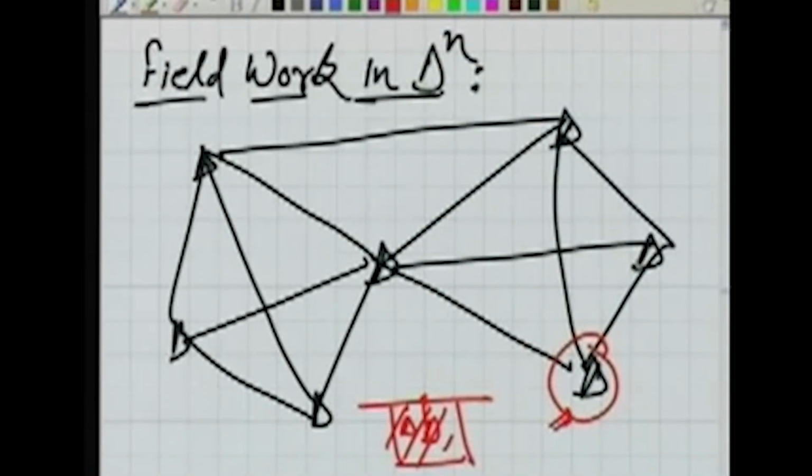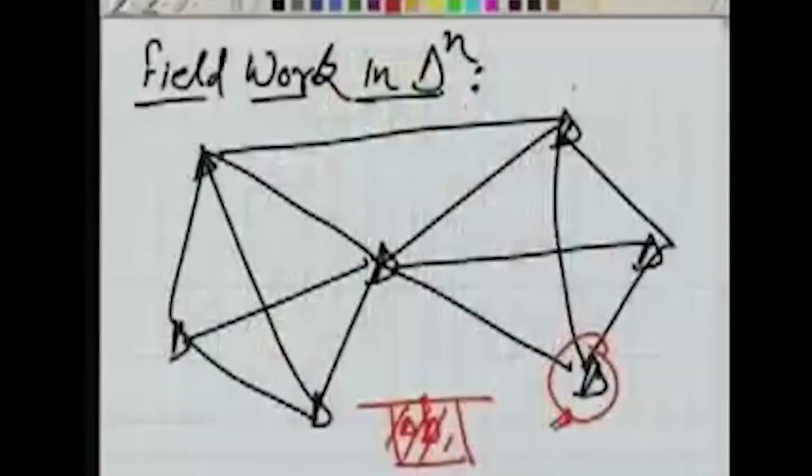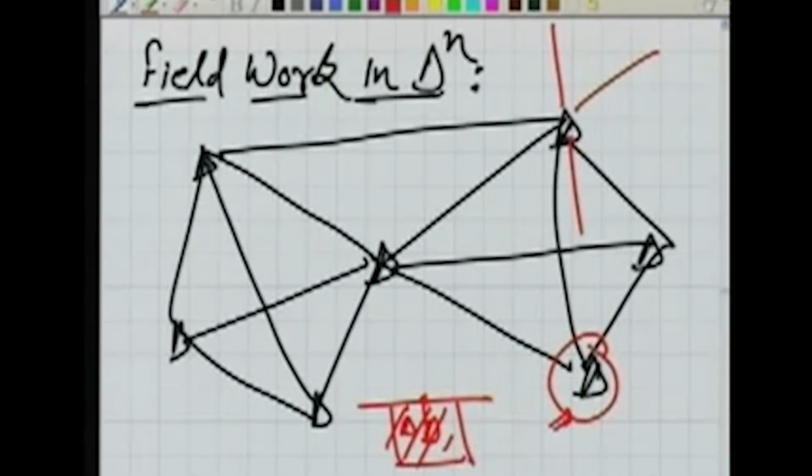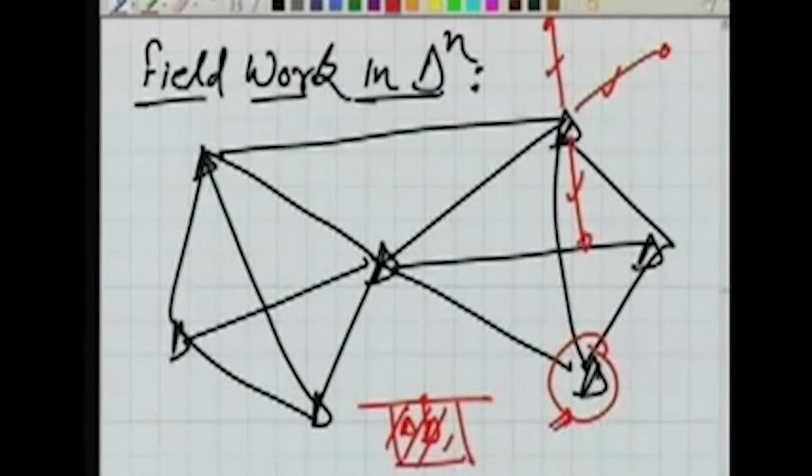As well, in order to locate these stations later on, we would like to take some witness marks from some permanent objects around. We will take these distances so that if we visit this area after 1 year, after 2 years, after 10 years, we can again locate our station, because this station is embedded in the ground, or it may get lost for some reason.